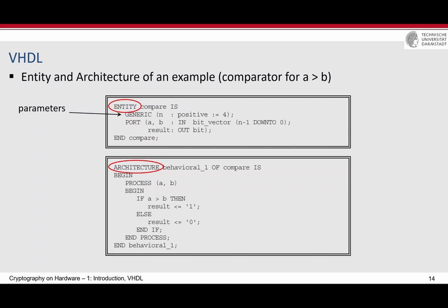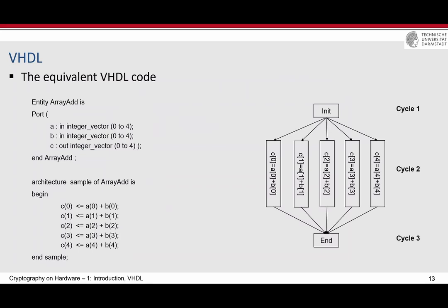Was the slide before, like in Verilog, we have always clocks, and if you want to have something change on the clock edge, you write always on clock. Is that combinatorial logic, or is that implicitly clocked? Combinatorial. Fully combinatorial, because there is no clock. And in Verilog, if you want to write this, it is with assign.